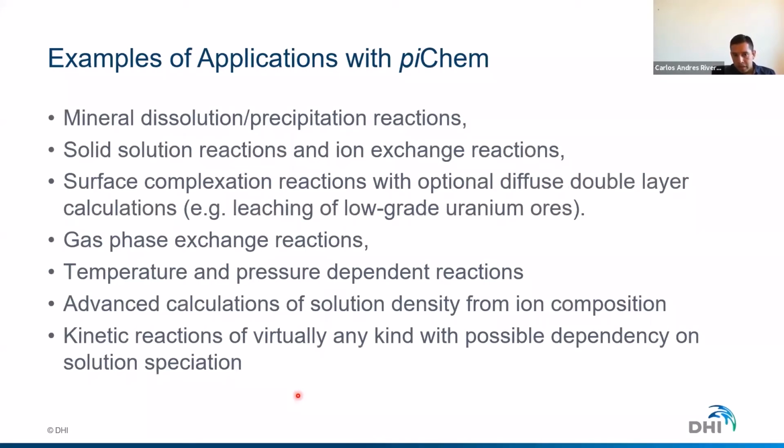What you can do is mineral dissolution, precipitation, sulfur reactions. You can include gas phase exchange reactions, so you can solve the gas phase in FEFLOW. You can, for example, provide the partial pressure of CO2, and then use this information to solve the biochemical processes. If you have temperature and pressure dependent reactions, you can use them in FEFLOW. FEFLOW solves heat transport, can send temperature information to PHREEQC, and the reactions can be updated on demand. And we can do complex kinetic reactions with FEFLOW, and also from the side of PHREEQC using the batch calculation from the software.